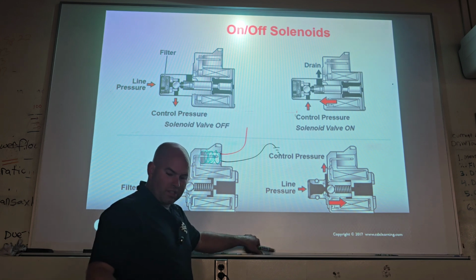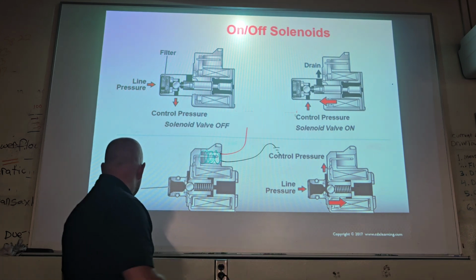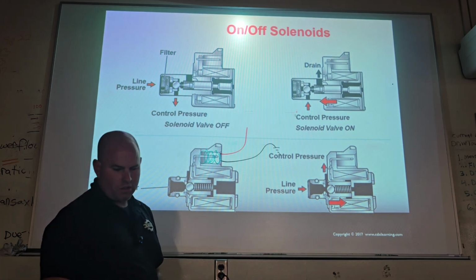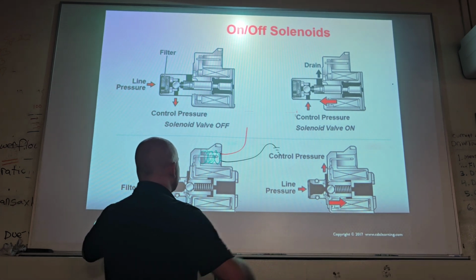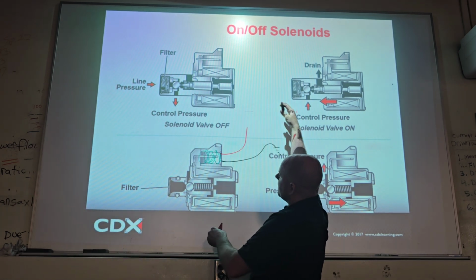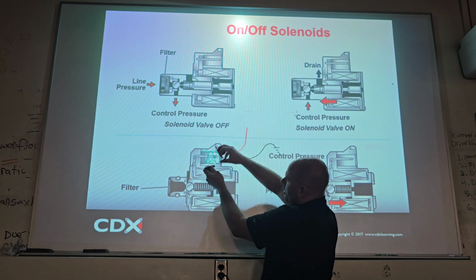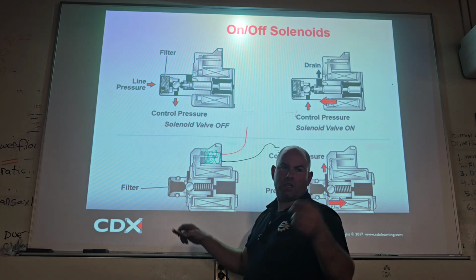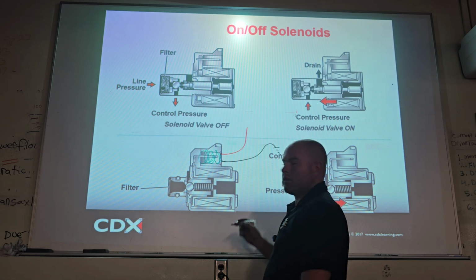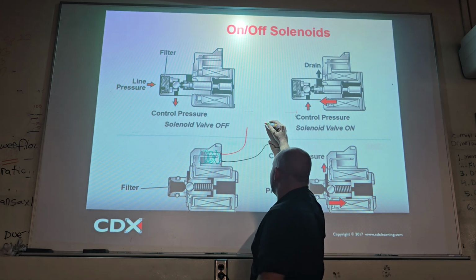I agree. Resistance. So you guys got some vehicles out there that have some shift solenoid codes. So you could literally put this thing on resistance, isolate it, right? Disconnect this here and here and measure it. What's the spec? I don't know. Does anybody remember a shift solenoid spec? Let's just say it was 4 to 6 ohms.